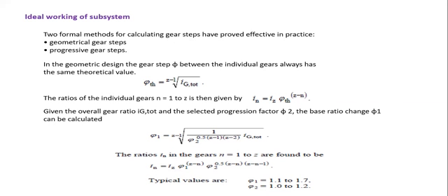When you keep the engine RPM constant, gear step tells you how much faster you go in upper gear compared to lower gear. On the other hand, it tells you how much engine RPM drops in upshifting or increases in downshifting. In more detail, there is a speed difference in the gearbox parts which you engage and disengage when you leave the current gear and try to shift to a new gear. This speed difference must be reduced to zero before the shift can be completed, and gear step tells you how large a difference you are about to reduce.